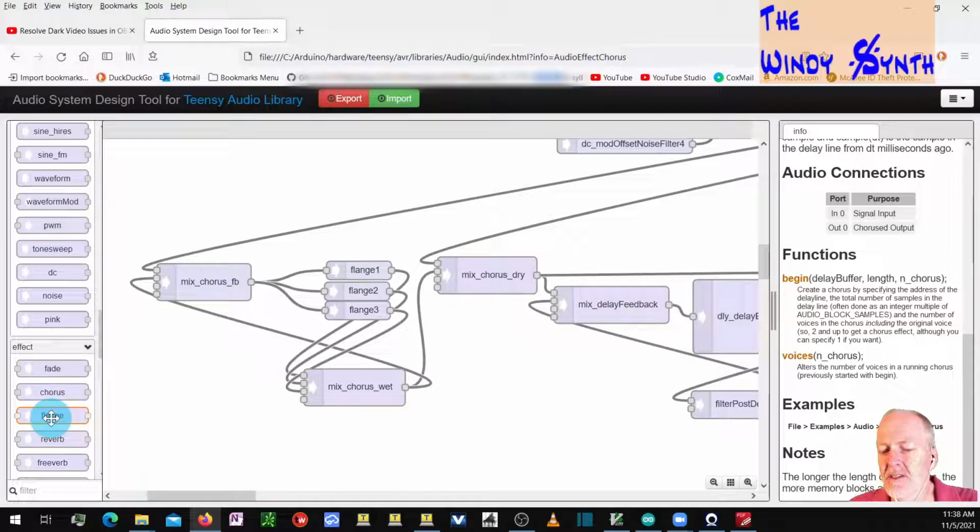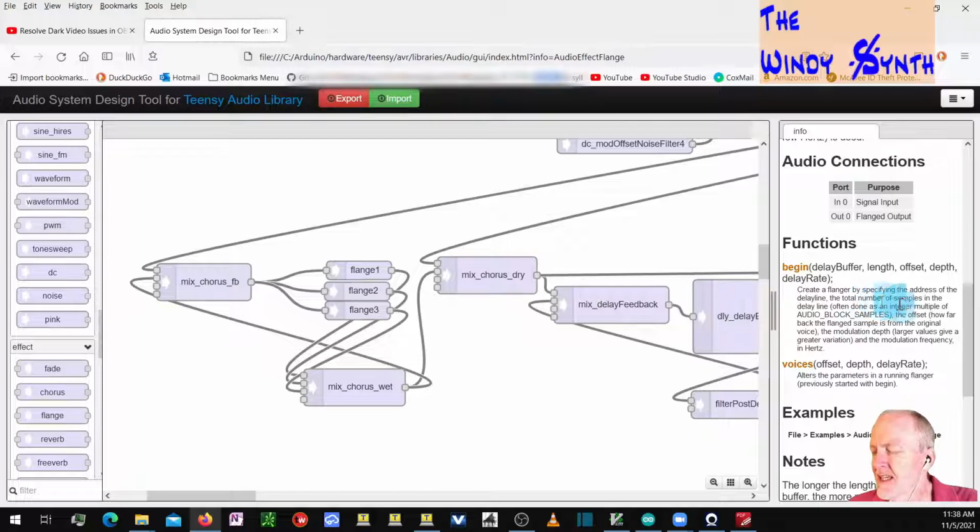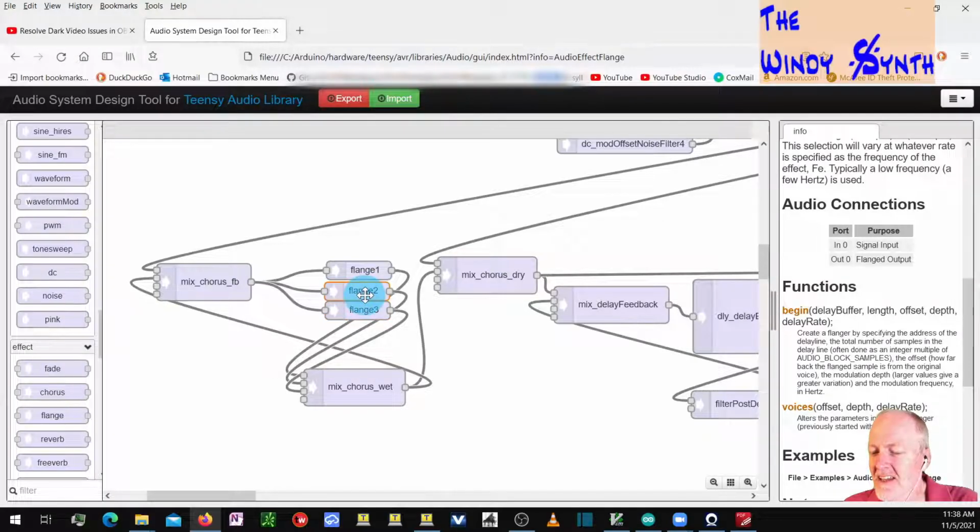So what I did was I took this flanger, and the flanger allows you to modulate the delay, but then there's the dry signal that's coming through too, and I didn't want the dry signal. I just wanted the delayed signal that you could modulate. So I took two flangers here, and then I took a third flanger and took the output of the third flanger in such a way that I subtracted it out of the other two, so that I was subtracting out the dry signal going through the two flangers, and all I was left with was the two signals that are modulated.